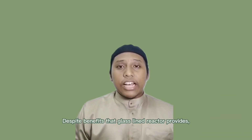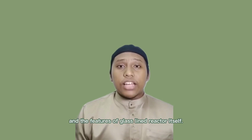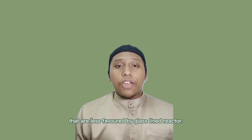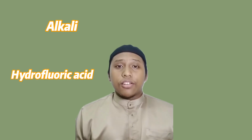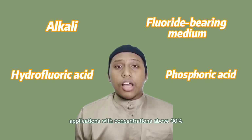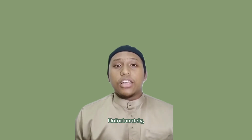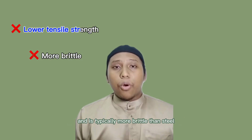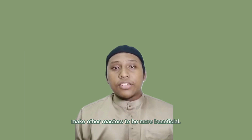Despite the benefits that a glass-lined reactor provides, there are still limitations to the application and the features of the glass-lined reactor itself. There are some chemical applications that are less favored by glass-lined reactors. This includes alkali, hydrofluoric acid, fluoride-bearing medium, and phosphoric acid applications with concentrations above 30% and at temperatures over 100 degrees Celsius. Unfortunately, glass-lined reactors have a lower tensile strength and are typically more brittle than steel or other metals. These shortcomings make other reactors more beneficial.